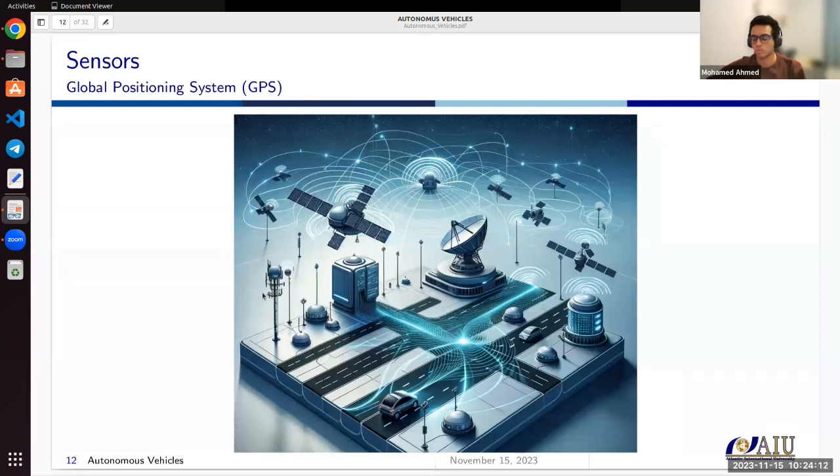Because one time we used a very good camera that cost about $1,500, but it was very hard to work with at a very high resolution and high frames per second. There is a limit. The Ethernet speed limit is about 100 megabits per second, and we had 3 cameras, so it was overflowing a lot.